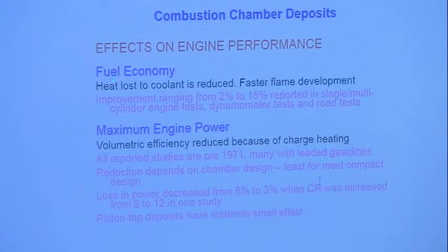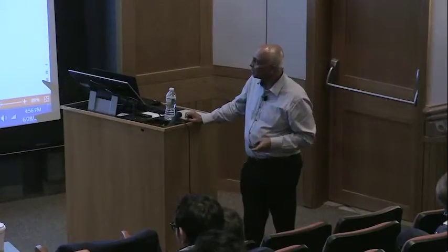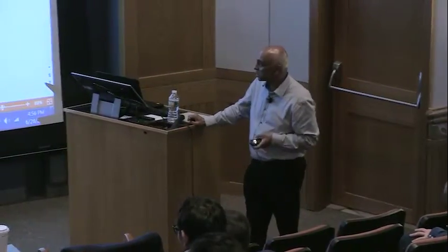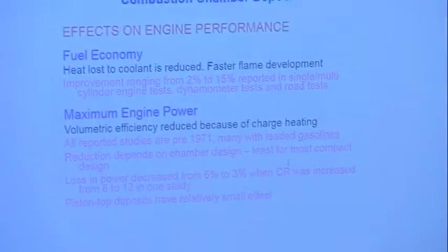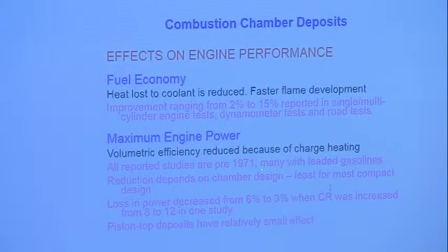And there's faster flame development, no question about this, because you can measure this. And heat loss to coolant is reduced. But it's not very clear exactly how this happens, what the mechanisms are. But this is a good area to study. Maximum engine power could be reduced, but most of the reported studies are pre-1971.